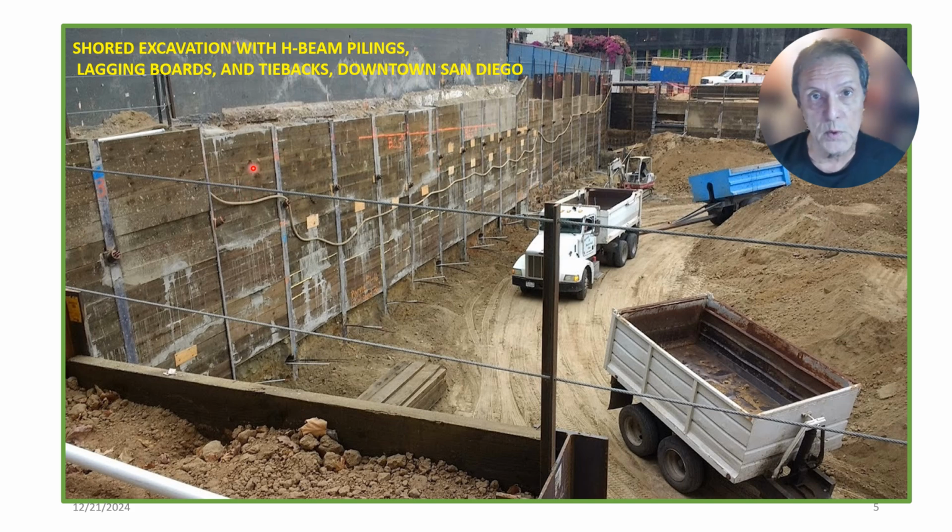Before these lagging boards are put in to obscure their vision, they can then map sedimentary structures, stratigraphy, look for indications or identify any faults which may be present within the walls of the foundation of the excavation.